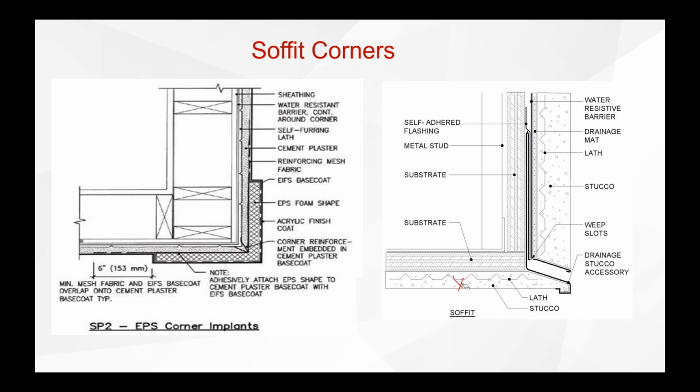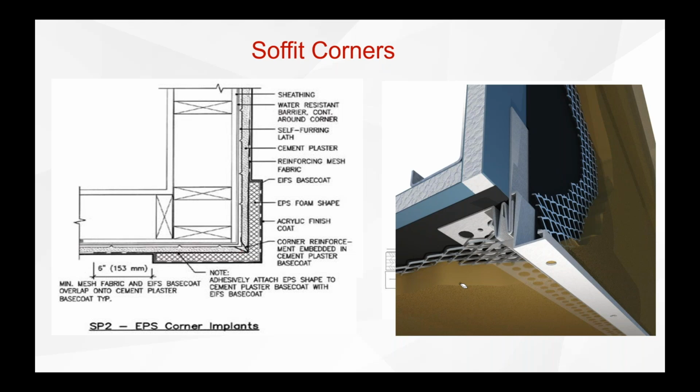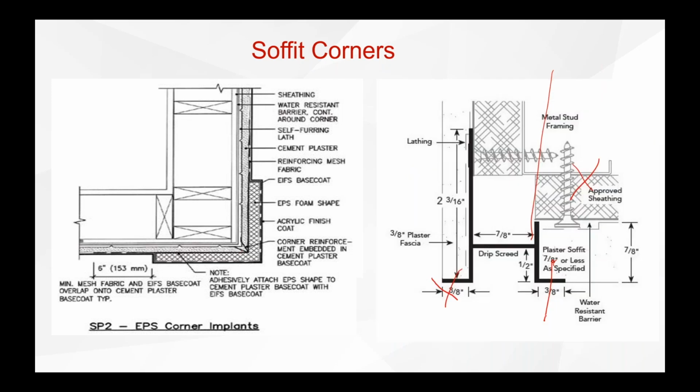So when you're designing your soffits, keep that in mind. Here's another way to do that. Again, this panel here is separate from this panel here. Water comes down, gets in these holes, and it can get out. So that's what you want to look for in a soffit design.